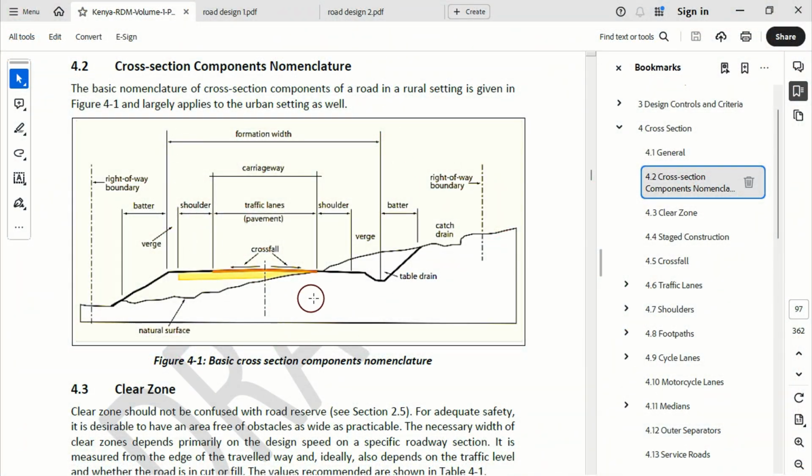From the road manual, we have the basic cross-section components of a road design given in Figure 4-1. The lane crossfall slope of 2.5% down runs perpendicular to the direction of travel. An assembly marker splits the cross-section to have the right and left sides, and this is the starting point of an assembly creation. We'll utilize this cross-section for Road 2 design as it contains an undivided crown road.